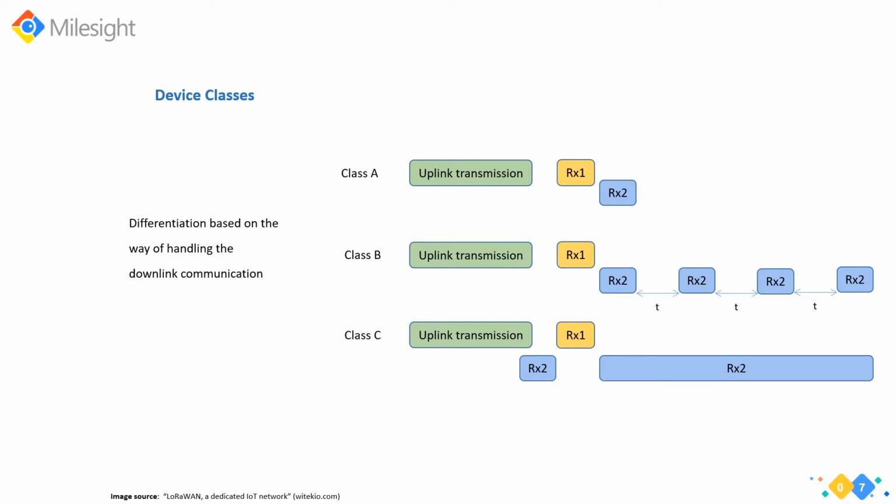So for example here, if you are using our Milesight IoT cloud for smart irrigation, and if you set up Class A, it means if you want to start the valve controller, the watering equipment, you need to wait about 20 or 30 minutes until the next time the end device sends a payload. But with Class C, there's almost no delay. So you can right now open or close the valve controller for watering from the Milesight IoT cloud.